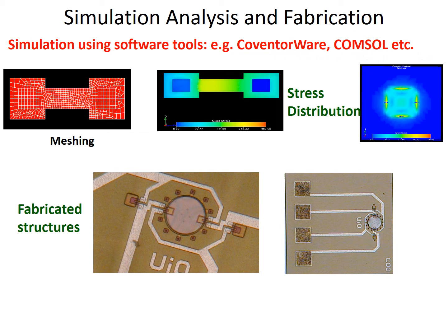And here, suppose for the pressure sensors, what we have to do is check that due to a particular amount of pressure, what would be the typical stress distribution, accordingly how much resistance change we can get, accordingly how much voltage can be generated. So likewise, these are the different factors. That type of thing we have shown just for representative purposes. Now generally these types of simulation tools are based on the FEM or finite element method analysis, and to do that we have to mesh it, right? Meshing means discretizing it into very small components, then we do the analysis. So here is some sort of simulation: for a particular amount of force, what should be the stress distribution. By the color map it has been pointed out here.